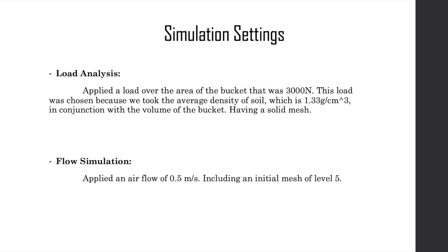We chose this load because we took the average density of the soil, which is 1.33 grams per centimeter cubed, in conjunction with the volume of the bucket, in turn giving us 3,000 newtons. And it used a solid mesh. For the flow simulation, we applied an airflow of 0.5 meters per second, including an initial mesh of level 5.